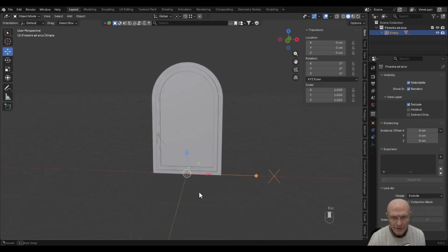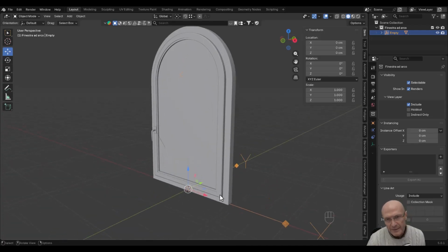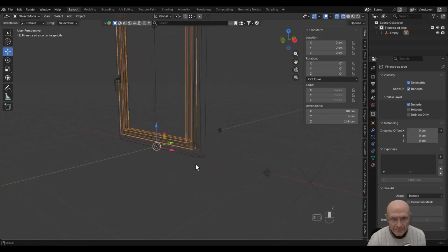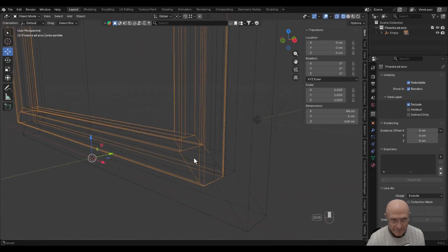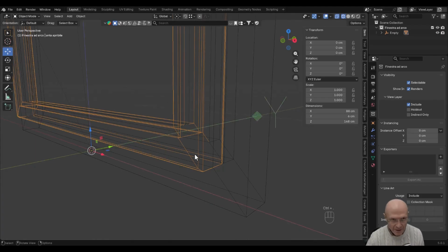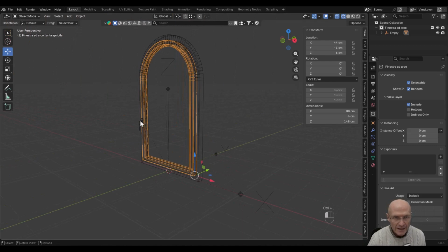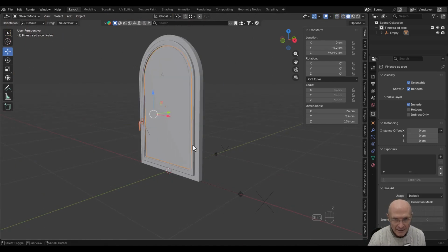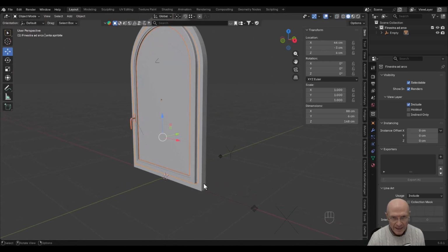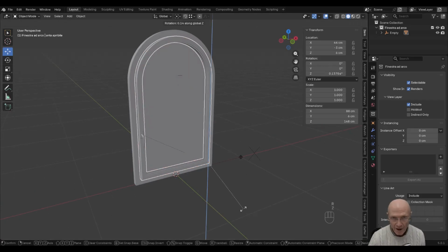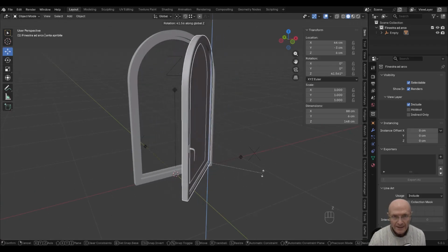Another thing we could do, for example, would be to open this sash along with the handle and the glass. So I'll select the opening sash, move the pivot point to this spot, then select the handle, the glass, and finally the opening sash again, Ctrl P, object. And at this point, if I select the sash, R, I press RZ, you see that the sash can be opened.